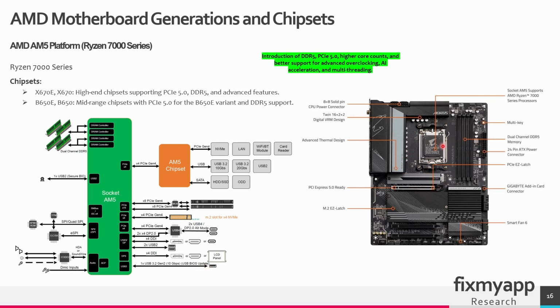If you compare this AMD board with the older versions of AMD boards, and also with the older versions of the Intel boards, it's still the same. The locations of the most important components are here: the back-end connectors, the CPU socket, DDR slots, 24-pin ATX power connector, the chipset underneath this heatsink, M.2 drives underneath this heatsink, PCIe slots, the audio circuit, and the CPU power connector. So for us, the physical layout is the same, and that will make it easier to pinpoint the components and how it should behave for analyzing and troubleshooting purposes.